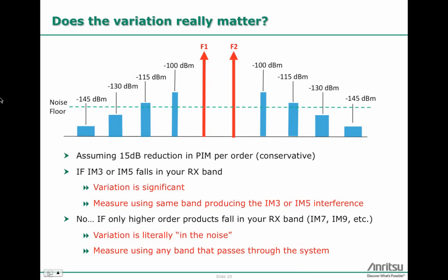And what that means is that you really should be measuring using test equipment at the frequency where those IM products are falling. So if the IM3 is being caused by 2 PCS tones, then you should be doing your testing on that system using a PCS test set.